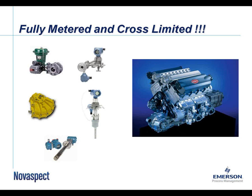But I would say all of these readings here you see are important. Airflow meters and gas flow meters are important. And then the actual outputs or the final control elements are important as well, especially if you're going to be characterizing those outputs. And if you have a draft control loop or you have an ID fan controlling draft in the furnace, you're definitely going to want to characterize the output of the air damper. The feed forward to the draft loop is the air damper output, and if you don't characterize it at low loads, you'll get a lot of noise, and at high loads, you'll get slow response.